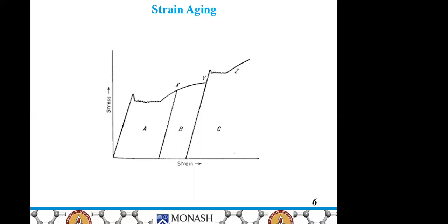So if the specimen is unloaded after point X and retested without any appreciable delay, without any wasting of time, then there will not be further yield point phenomena observed in this case, since the dislocations have been torn away from the atmosphere of carbon and nitrogen.